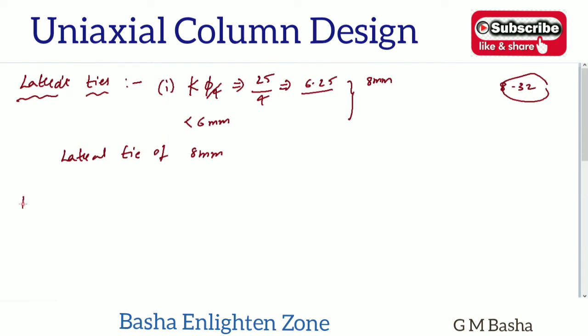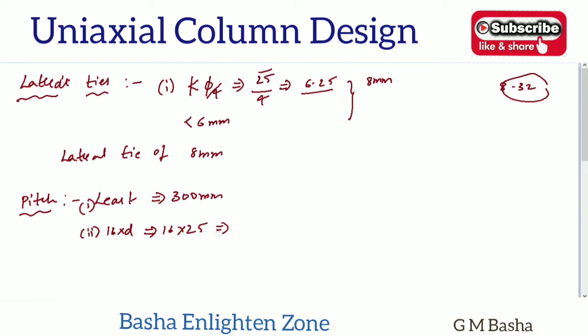And pitch, which is the spacing in beams, but here we call it pitch. The first one is the least lateral dimension of the column. So the least lateral dimension here is 300 mm. The column size is 300 by 600, so the least lateral dimension is 300 mm. And the second one is 16 times the diameter of the longitudinal bar. 16 into what is the diameter of the longitudinal bar we have taken here? 25. So 25 into 16, around how much will you get?